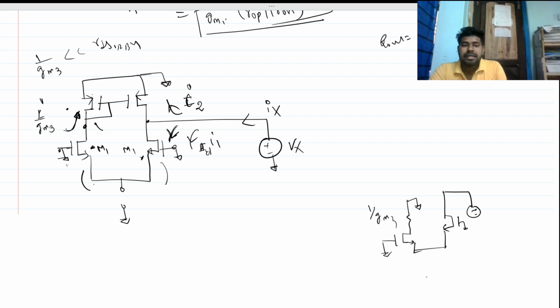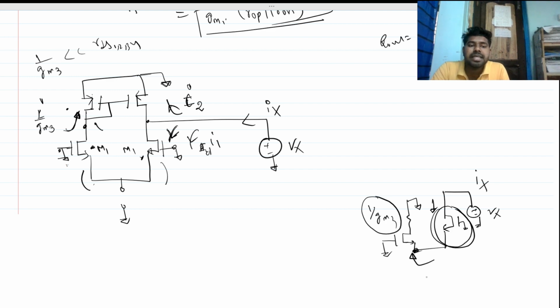Now for this MOSFET, if we look from here, basically this is an NMOS with a source degeneration, right? Now looking up here, what is the impedance? Because this is a finite impedance, and very small compared to the RDS of any MOSFET. So looking up here is nothing but 1 over GM1, because this is M1 and this is M2. The looking-in impedance from the source of an NMOS is nothing but 1 over GM.